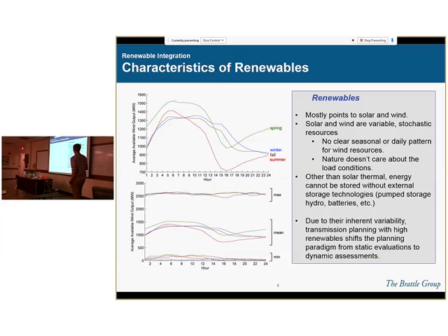And so putting this back in the transmission context, if you're looking at a single snapshot of the system to see if the system will be stable, or if the supply-demand balance or the reliability criteria will be met, if you go from one hour to the next, the renewable output may change considerably. But if we're looking at single snapshots of the system, we can't capture that. There are other aspects of this too: this tremendous variability requires additional flexibility in the system.